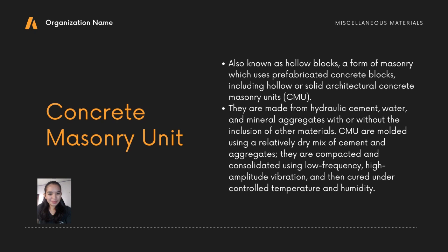CMU are molded using a relatively dry mix of cement and aggregates. They are compacted and consolidated using low-frequency, high-amplitude vibration and then cured under controlled temperature and humidity. These units are suitable for both load-bearing and non-load-bearing applications.